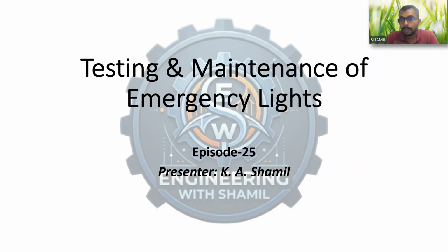Okay, so again, to refresh our memory, emergency light is actually an equipment which works during the time of power failure. So again, emergency light is of two types. We have the maintained light and we have the non-maintained light. Normally when we install an emergency light, it will be in the off state during the normal operation, and it will be on during the power failure condition. So this category of light is the non-maintained emergency light.